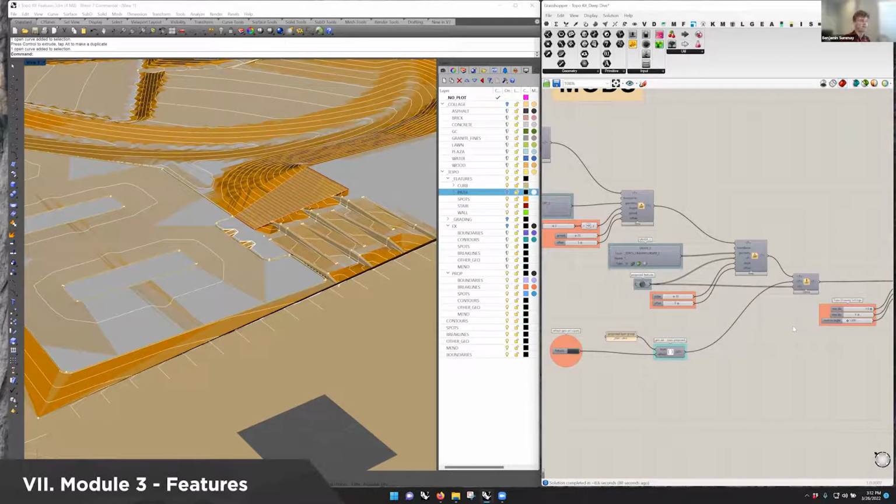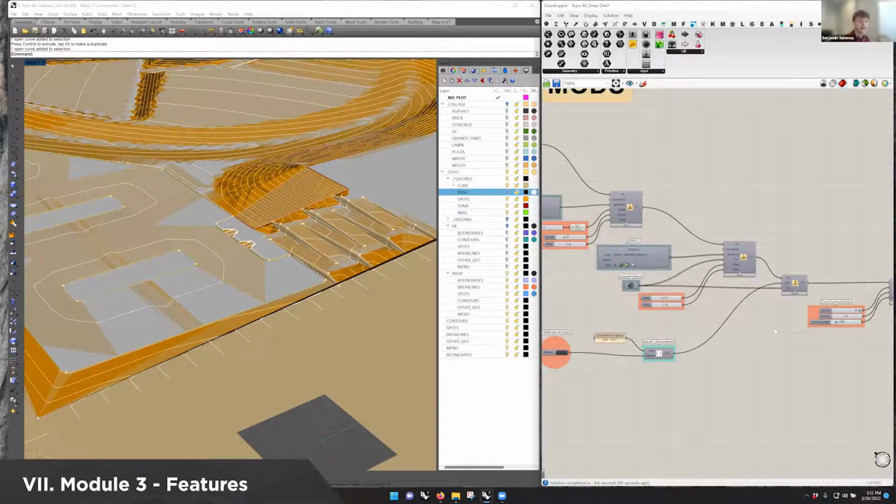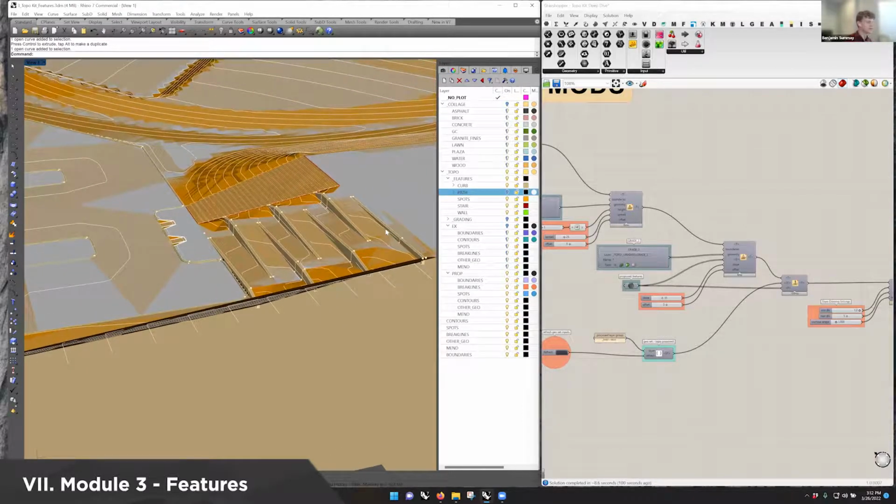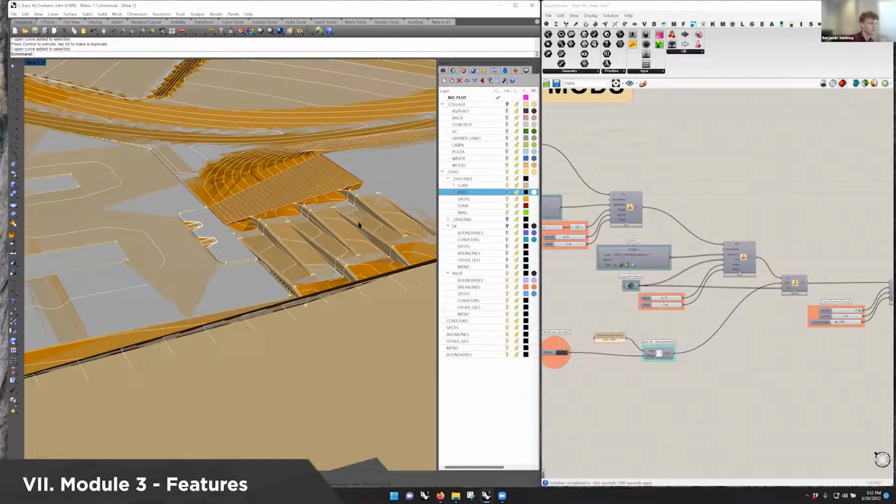Think of them as retaining walls, as you're just trying to adjust the grade, not necessarily add chamfers to your walls or things like that yet. There will be mods coming that will do things like that. You can add wall above the grade line of the wall and stuff like that too. But for now, the good way to think about it is I'm just trying to regrade the topography. So I want the back top of my wall to be where the level plane of the topography will be.